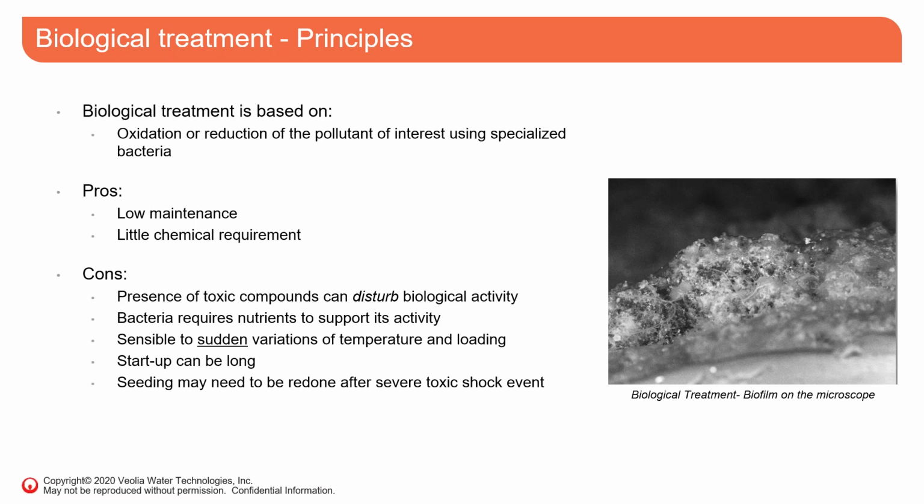Biological treatments are sensitive to sudden variation of temperature and loading. We're not talking about gradual variation, such as when the snow is melting on site. It's a really sudden variation, like a chemical spill.